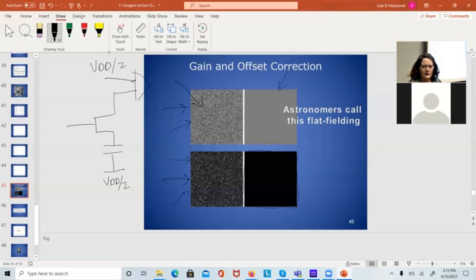The next thing was, okay, I'm going to power down the entire DRAM. I'm going to write 1s into the entire DRAM chip, and I'm also going to try writing 0s into the entire DRAM chip. If I write 1s in, because you know with this VDD over 2, it should have like a 50-50 chance of coming up at around VDD over 2.